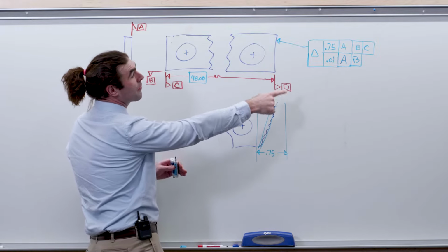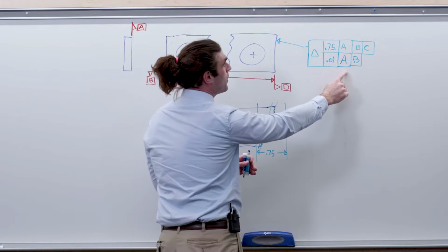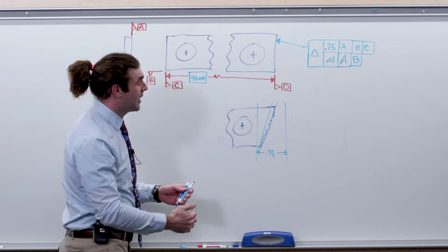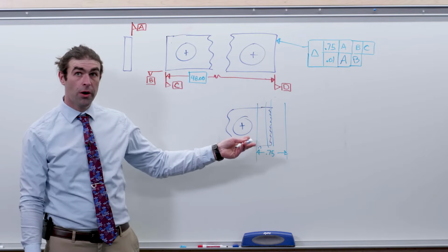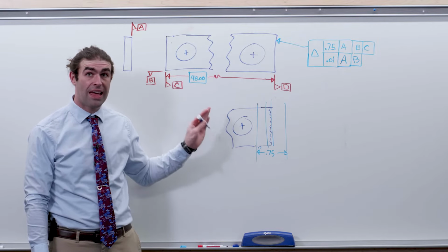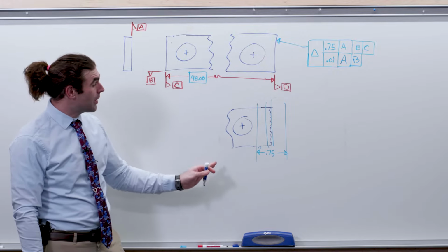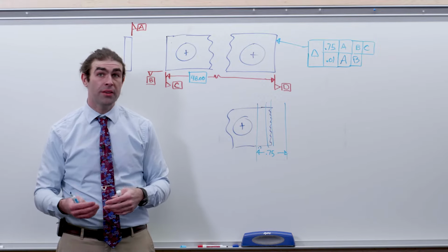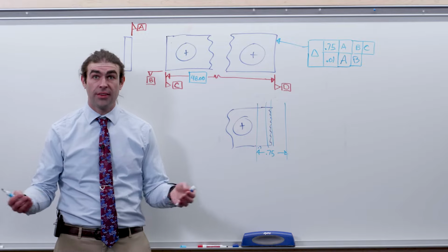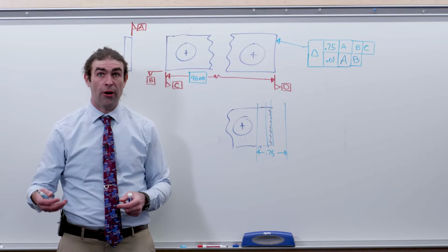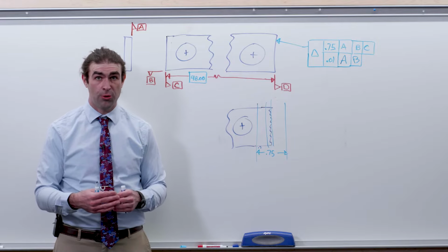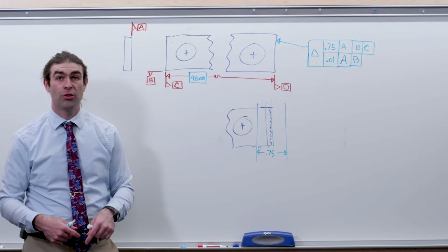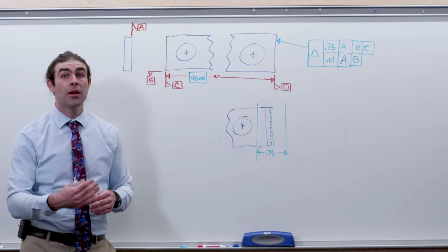So now we've got to be flat to 10 thousandths. We've got to be perpendicular to datum A, which is the largest surface, and perpendicular to datum B. So what that does for us is control the perpendicularity of this surface to A and B, and the flatness, but it can still float within this 0.75, which, in my opinion, for the limited function of this part, is a success. Okay, so that's what composite profile can do. Now, normally composite profile is applied to more than one feature, so a pattern of features, but it can easily be applied to a single feature to give the designer more control.